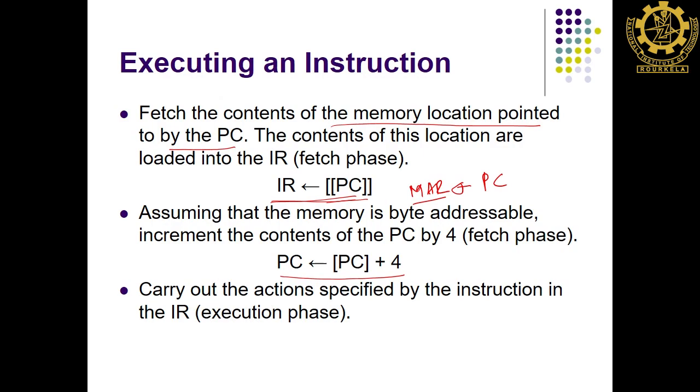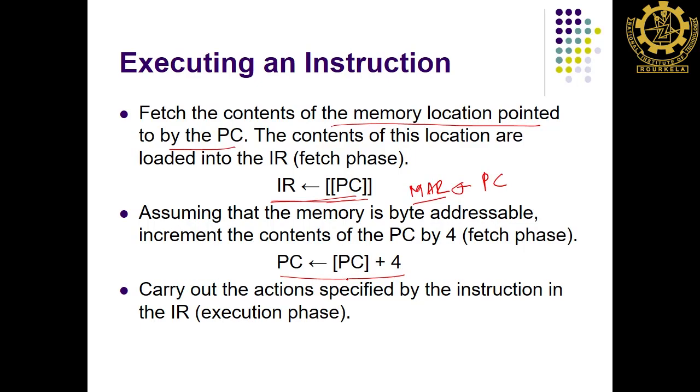Any operation that happens involves the ALU, because the ALU is the only circuit where we can do addition, subtraction, any logical operation, shifting and so on. So whatever the program counter value is, it will be added with 4 and then stored back to the program counter. Then it will decode the instruction, and whatever the operation is, let us say addition, that needs to be done. In a very abstract way, these are the 4 steps for executing the program.